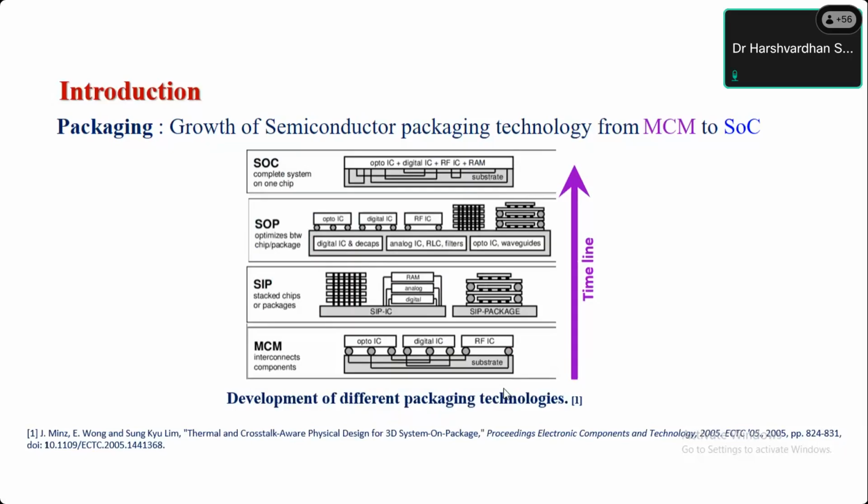But there were some challenges also. When we are designing an MCM module, suppose one RFIC is damaged, then we can remove that RFIC and put in a new one, and our system will be working. But in the SOC case, that is not possible. All those ICs are kept in a single package, single chip, single wafer.